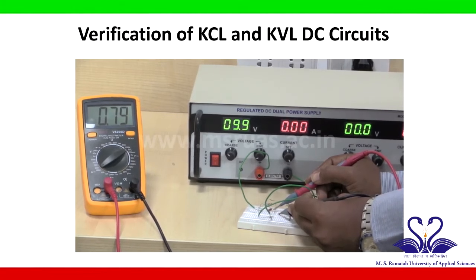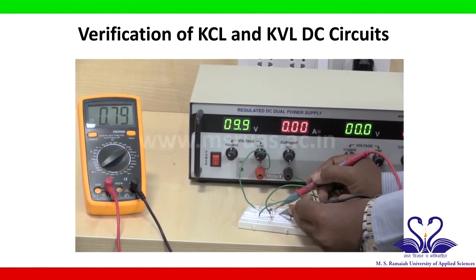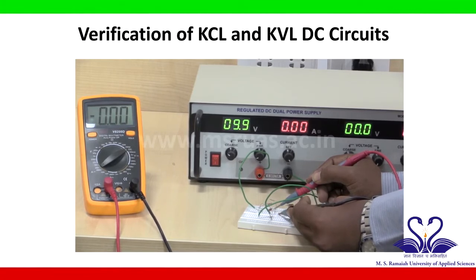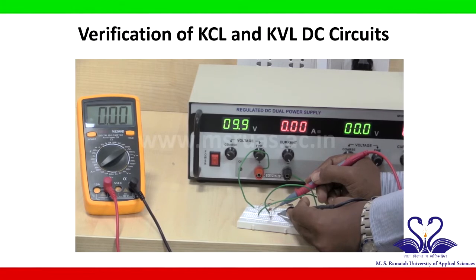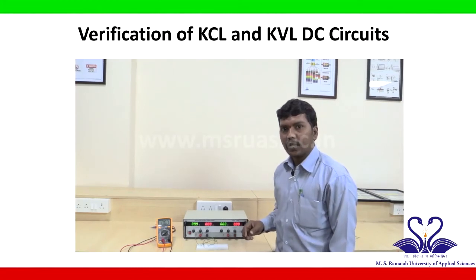And from this you can observe that the current I1 is showing 3.05 milliamperes, and I2 is showing 2.25 milliamperes, and I3 is showing 0.79 milliamperes. So according to the given circuit, I1 is equal to I2 plus I3, so that you can verify the current relationship. That is nothing but 3.05 milliamperes is equal to sum of 2.25 milliamperes plus 0.79 milliamperes. Hence the currents are verified according to the given circuit.